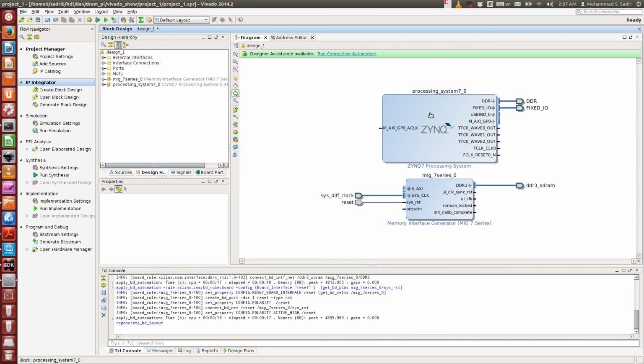So for now we have two components, and now you have, in fact, the DRAM controller here on the ZYNQ PL. What do you want to do with it? So this DRAM controller is providing you an AXI slave interface, and now you can instantiate your AXI masters in the ZYNQ PL, and the AXI masters can get connected to this AXI slave interface, and then through this interface they can directly write to your DDR memory and read from it.